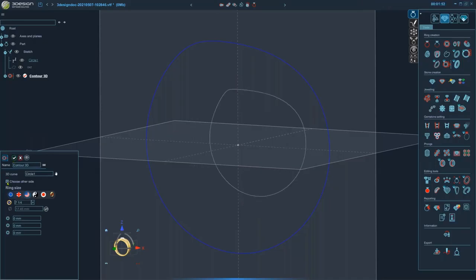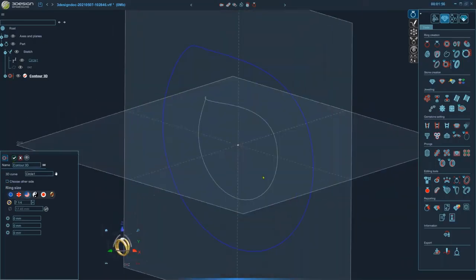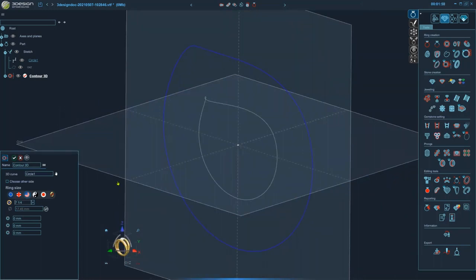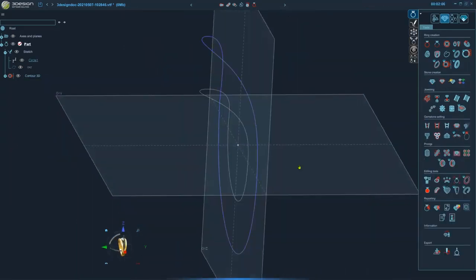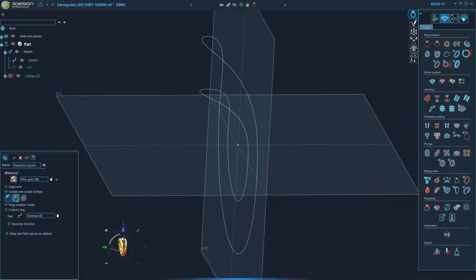You can also use this to move it to the other side of the plane. That's good if you're going to run this twice for setting up a 2-rail sweep with this as well. But I'll just use the 1 rail. Show you a nice example of this. I'm going to go ahead and sweep this with a sweeping wizard. Give it a section.